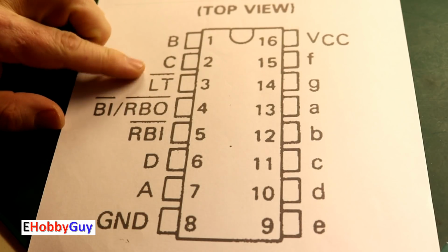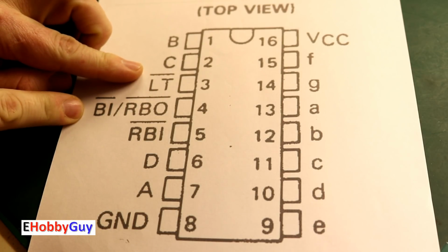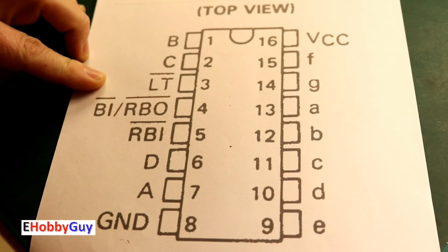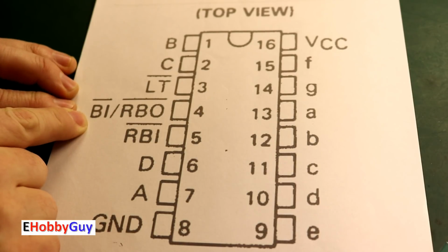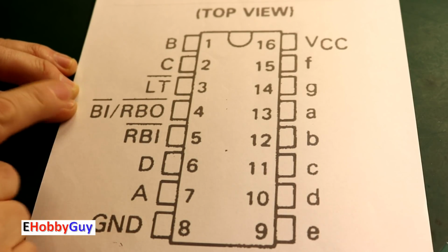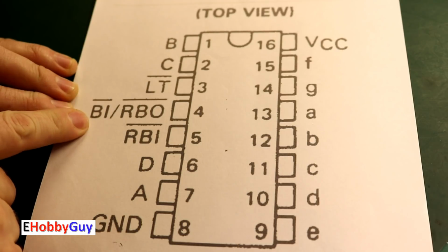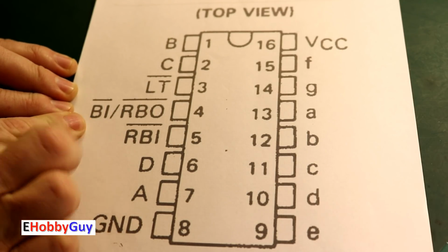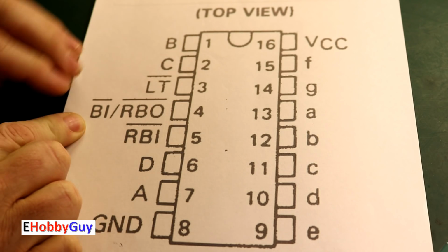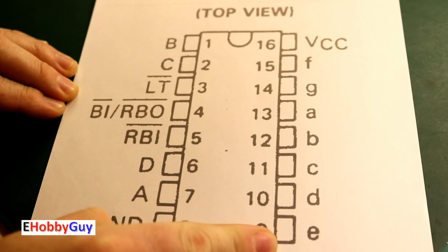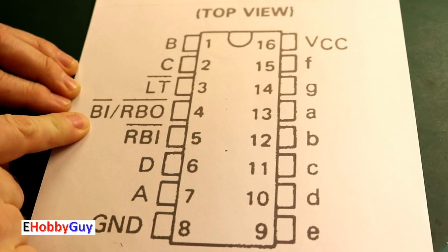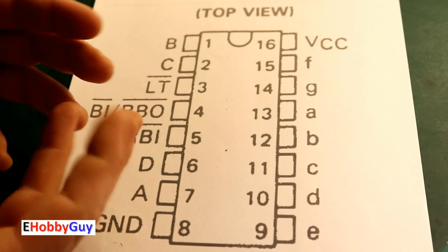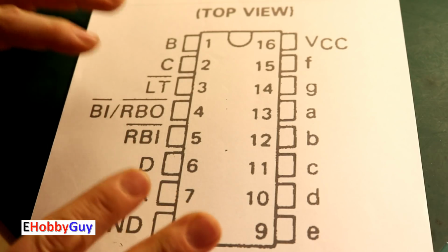One thing to note about the lamp test is that the blanking input needs to be high if the lamp test is pulled low in order for all of the outputs to become active. Now BI here stands for blanking input, and again it's active low. Now the blanking input can be used with pulse width modulation. So we can use pulse width modulation to blank this at a very high frequency, controlling the intensity of all of the outputs. And so that's typically how blanking input would be used. You could also just turn it off completely if you didn't want it to be seen, depending on the conditions and the application that you may be using it in.